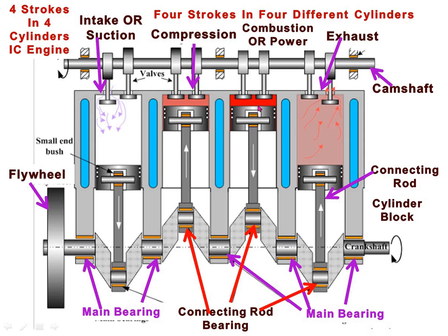So due to the heat of compression, the fuel that has been injected starts burning, and it produces hot gases with high pressure. It exerts pressure on the piston, and the piston travels from top dead center to bottom dead center. That is the power stroke, or combustion stroke.